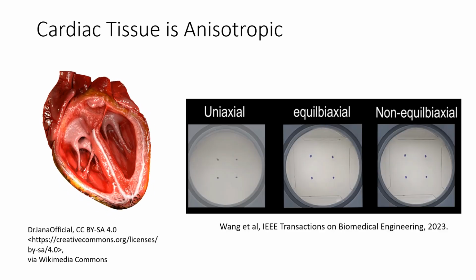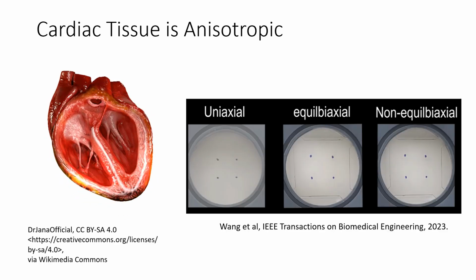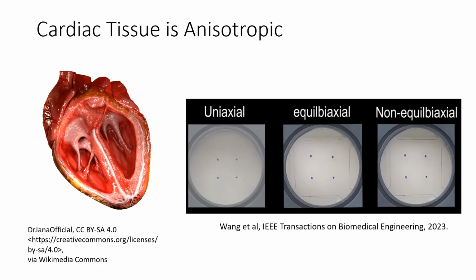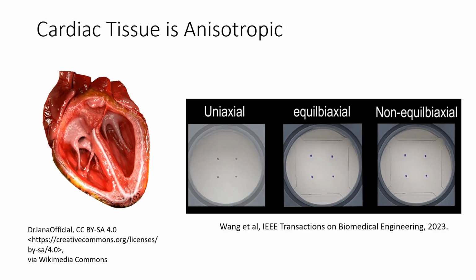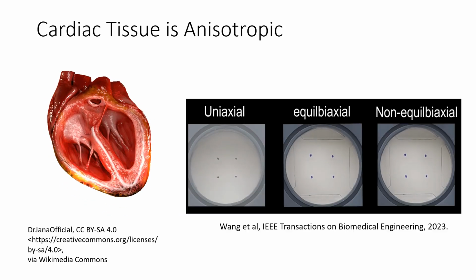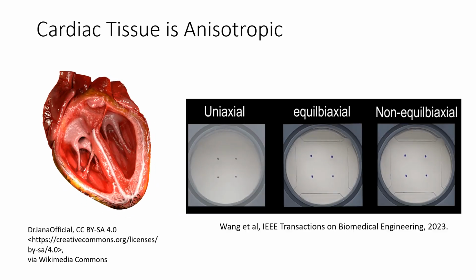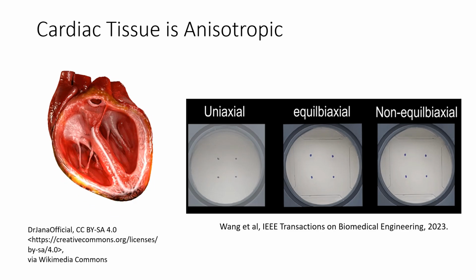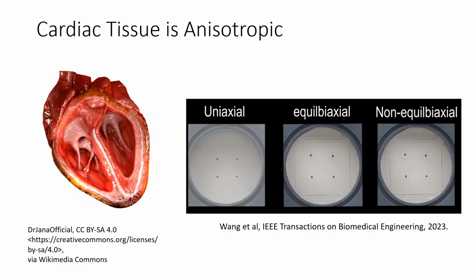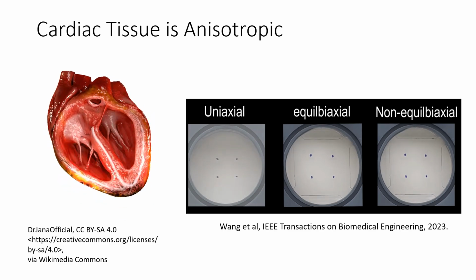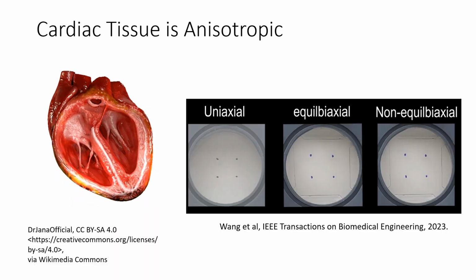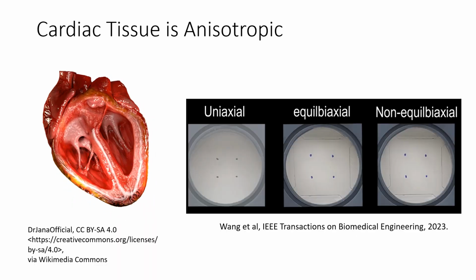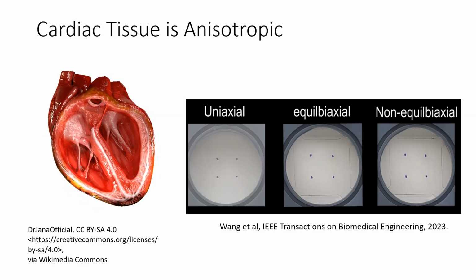Our lab has developed a microphysiological system for doing in vitro mechanical stimulation that resembles the mechanics of the heart. We have two sets of vacuum chambers that induce strain in an elastomer membrane that we grow the cells on. By applying different pressures of vacuums to the different actuators, we can achieve strains that range from uniaxial to biaxial. We'll use this system to practice calculating stresses and strains.